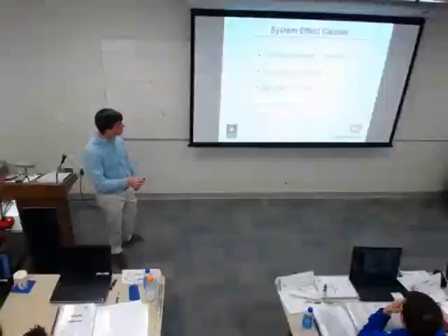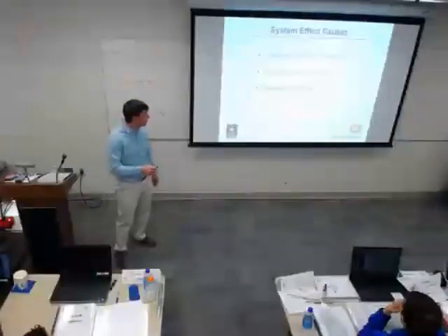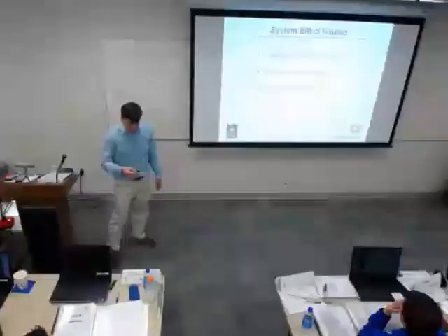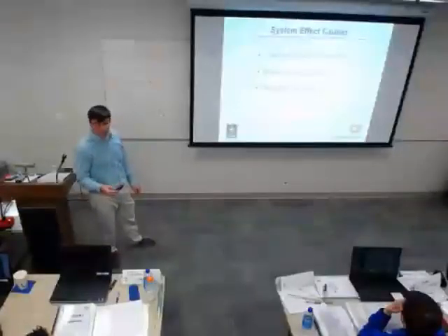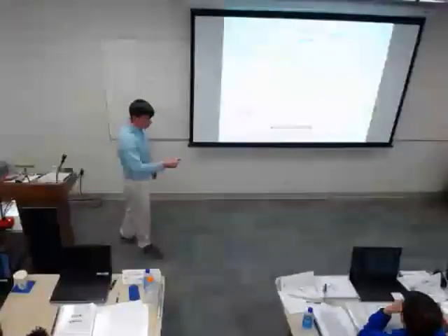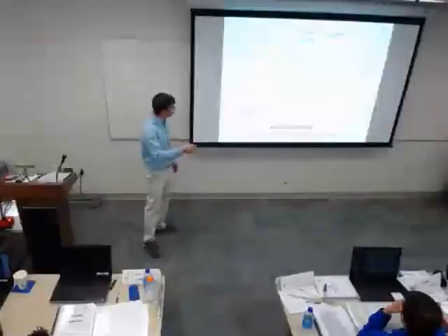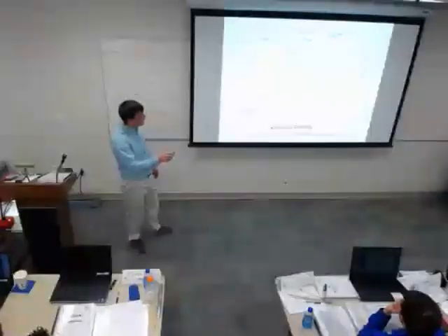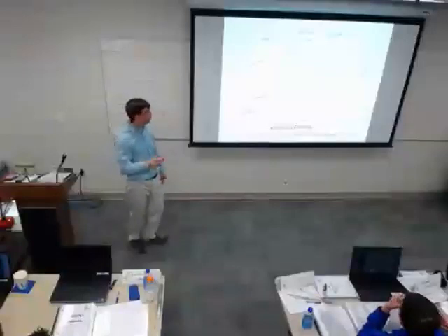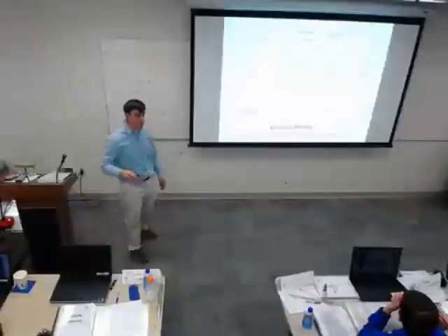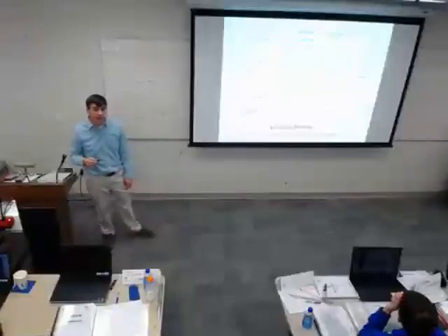I'm going to show you what I mean by effective duct length, elbows at the inlet, and blast area over outlet. Those are the things that go into whether I am going to have system effect that I need to worry about. So when the fan wheel is spinning, the outside portion of the fan, the farthest tip of it, is going to have the highest velocity. I'm showing here it's going to take a little bit of duct before I get a uniform velocity profile downstream of the outlet of that fan.